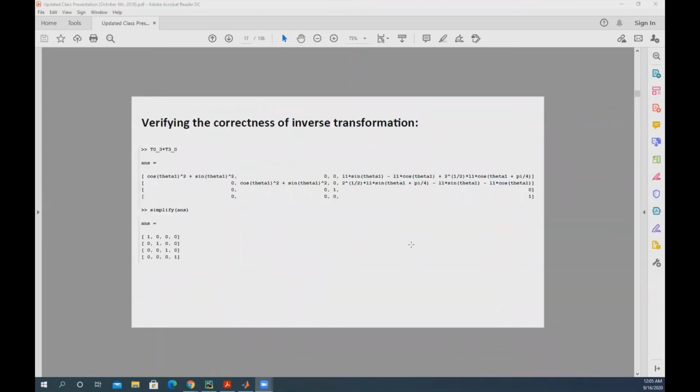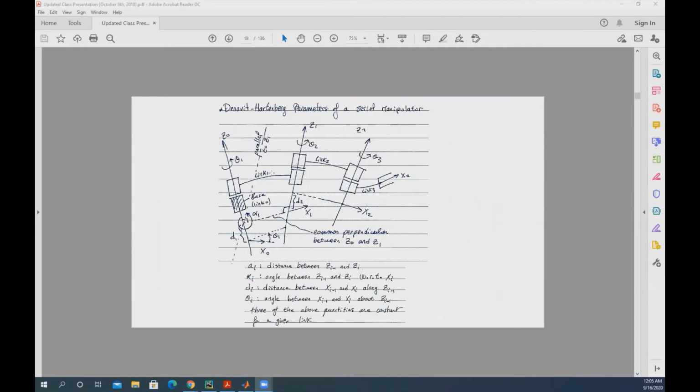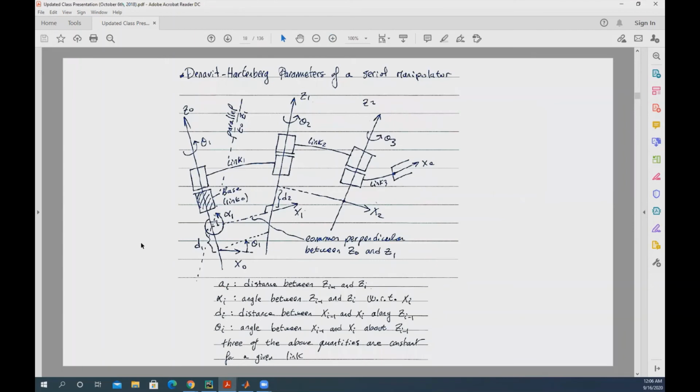So here are the DH transformations. If you are working with an articulated robot with many axes, you might want to work with a conventional method for putting the frames. We said every link on the robot will have its own frame, but where you actually put the frame is up to you. Ultimately, your goal is to perform transformations between the end effector, or where the robot is, and your base frame.